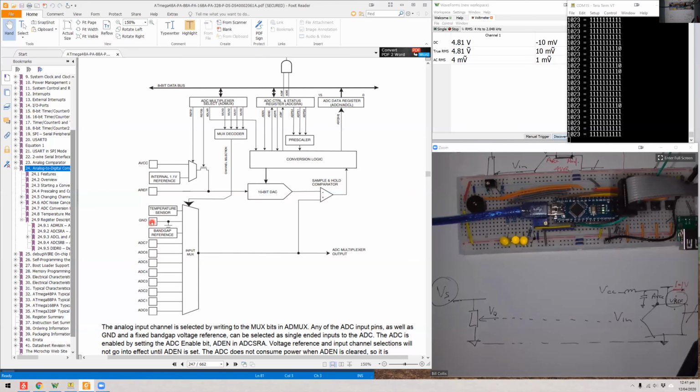Everything that happens in our microcontroller is under a little bit of influence from temperature, so we've actually got an internal temperature sensor that we can measure. We can build in compensation using a bit of math for variations in our internal reference voltage by measuring that, measuring ground, measuring the temperature, and then thinking about how we might adjust our equations for doing conversions appropriately, depending upon how our system might be different.